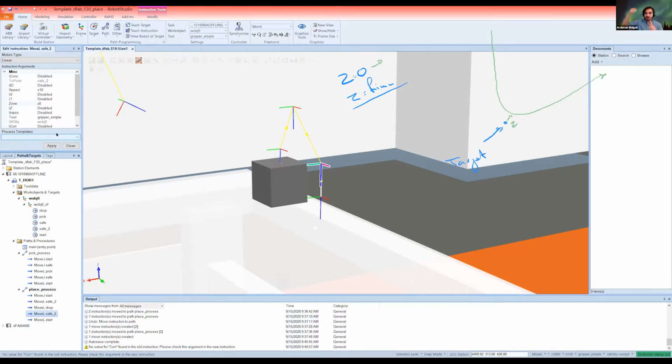So in Z0, the robot moves like this, almost touches the target, but it smoothly goes away. In fine, it means that the robot goes there, stops there, touches that, and goes away. So it seems like not a big deal, like stopping at the target, it seems fine. But once you start working, for example, with a hot wire cutter, or if you start painting with the robot, or anything that's time sensitive, that quick, small gap, the hiccup, is going to be essentially ruining everything.